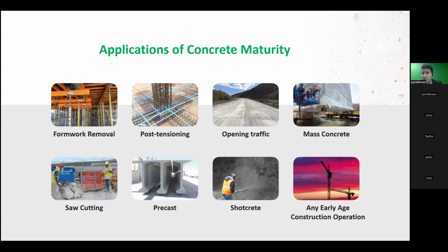Yes, because you can actually identify that. And more than this, we can also measure both the compressive and the flexural strength. That is approved by code. So if you have a DOT project, let's say a pavement where your target is not 5,000 PSI, it's actually 400 PSI because it's flexural, the sensors can actually measure both. You just need a calibration and then you tweak between flexural and compressive, and the system just back calculates everything on your behalf.